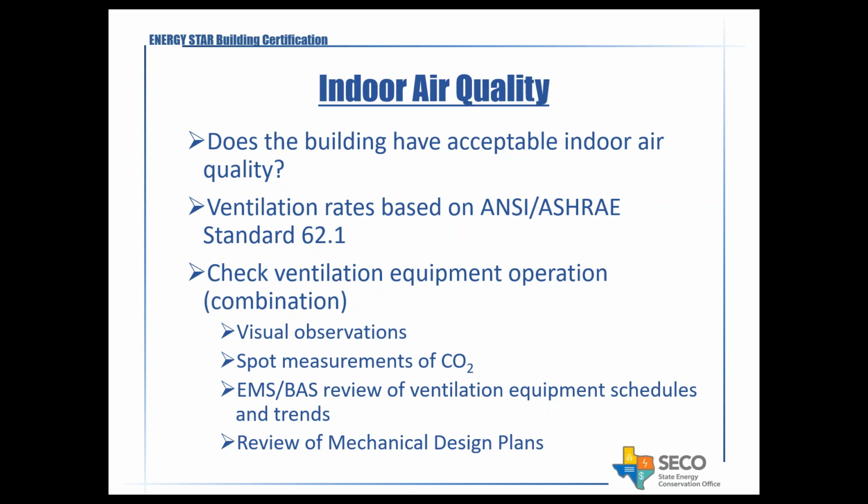This one is pretty important to pay attention to, because you may have a score of 75, you may also have good light levels and everything else, but if the indoor air quality requirements are not met, which means that you have the dampers closed during occupied periods, or you have high CO2 levels and so forth, that may not qualify for the Energy Star certification.